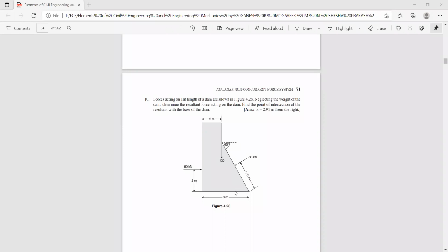So now this side, that is AC, is nothing but cos theta. Cos 60 is equal to AC divided by 1.25. You will get this distance. So you deduct from this point to this point, you require the distance. This total is 6, so you deduct this AC length, then you will get the remaining distance. Hence the perpendicular distances for this component forces are the opposite side and the adjacent sides of this small triangle. So finally find sigma MA at this point, considering all the forces.